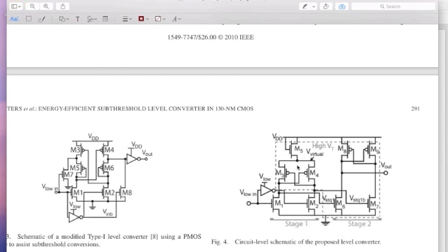That way, what happens is this voltage here is one diode level down. When we say diode, it's a transistor MOSFET based diode. When you connect the gate and the drain together, it basically is like a diode. So you have one VT of the NMOS lower than VDD. So you are effectively creating internally a lower supply for the first stage without having to get it from outside.